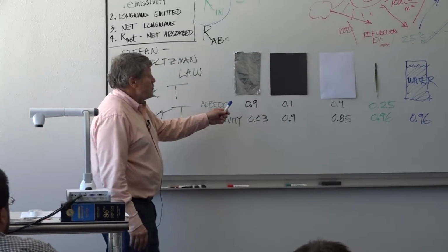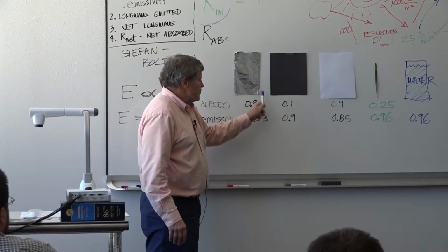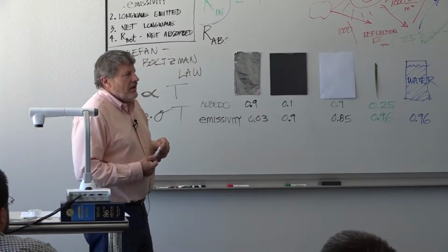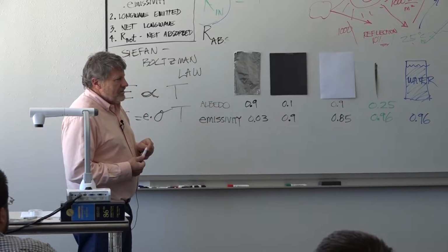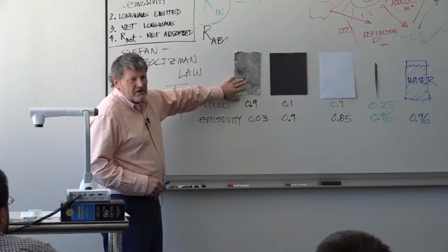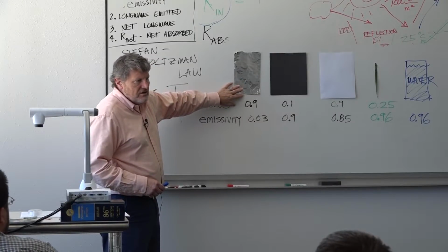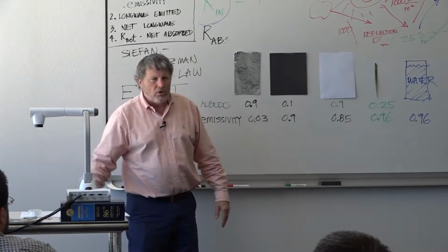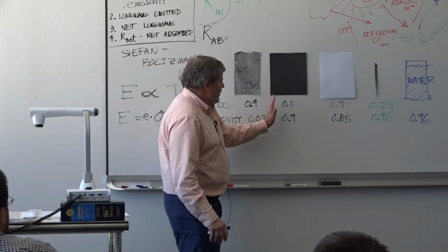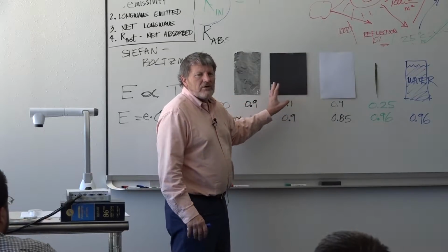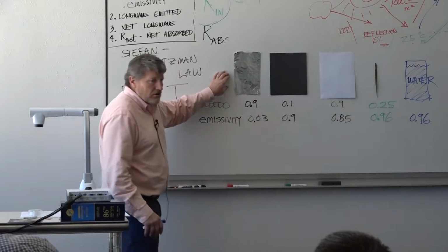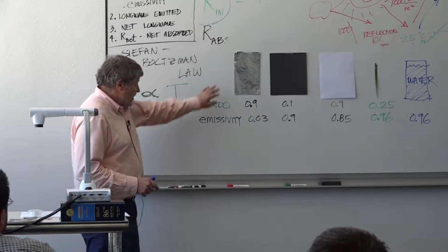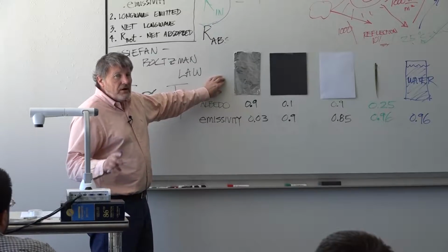So you would think there's a lot of things in between here, between these two for emissivities, and there are, but not as many as you might think. All polished metals have low emissivity, but most building materials, bricks, white walls, stucco walls, are all up in a higher emissivity. The only things that are really low are shiny objects, but they're a nice example because they're really low.